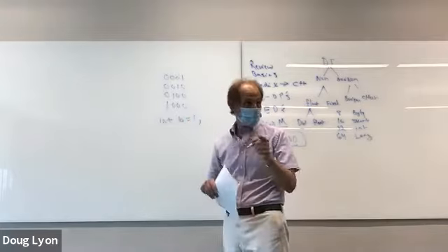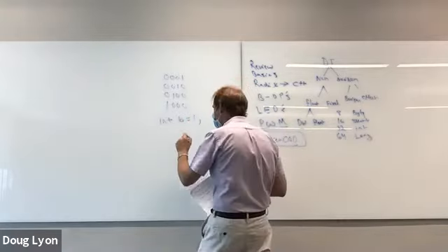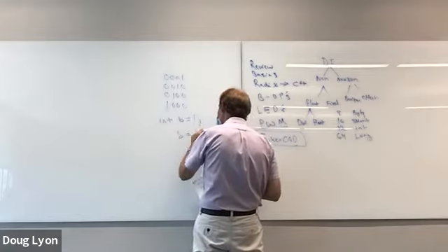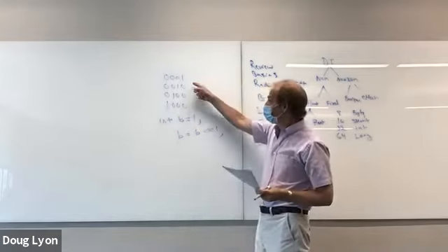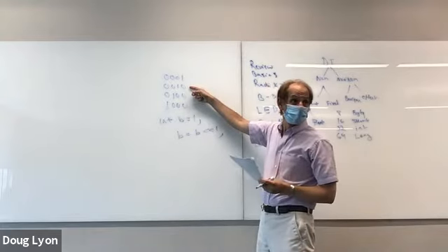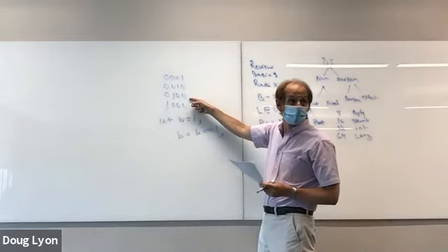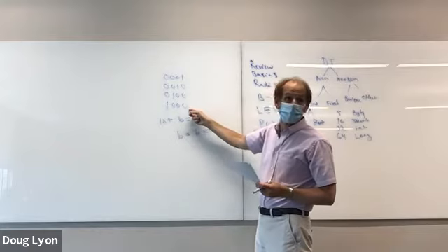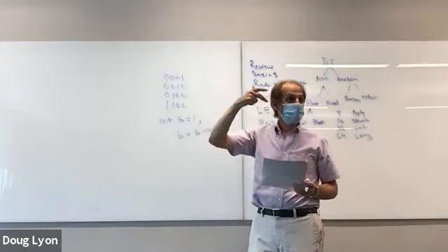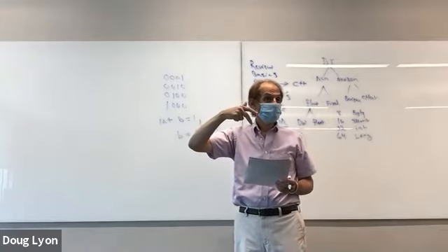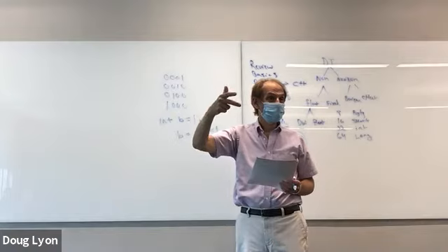Then if I want to shift to the left, I can say b equals b shifted by 1. And now b will be equal to 1, 0. If I do it again, it'll be 1, 0, 0. And if I do it again, it'll be 1, 0, 0, 0. Well, this is great, because now I don't have to write a whole bunch of code in order to figure out what the pattern will be for my LED.